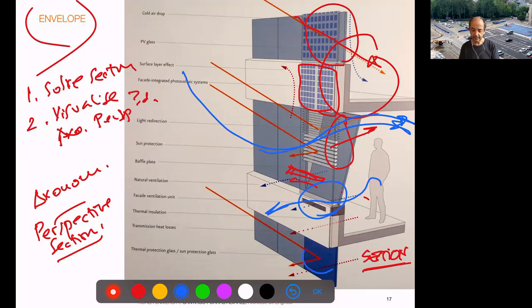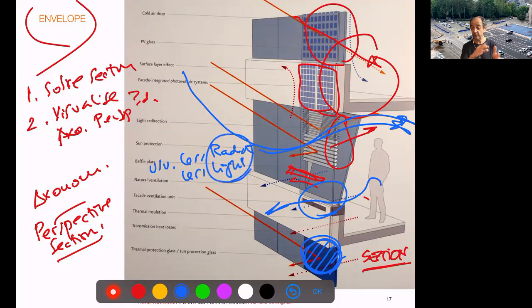And finally, some of you mention very often this kind of solar protection glass, in which you have less radiation. But remember that usually less radiation means less light also. So you might be saving on one side, but not on the other. Even a small radiation filtering may reduce the light you get in by 50% or more.